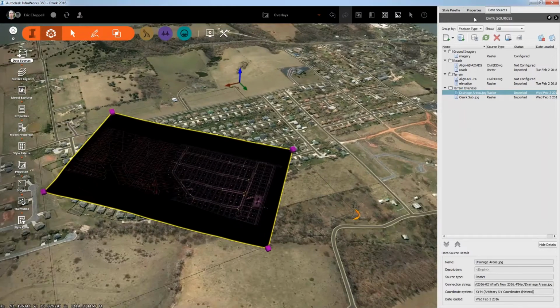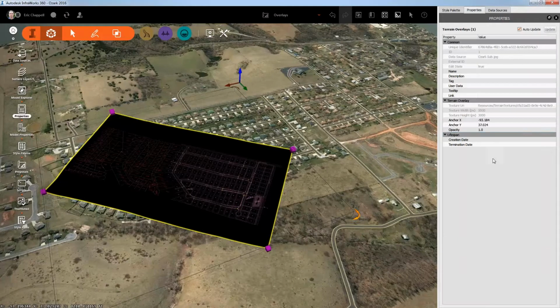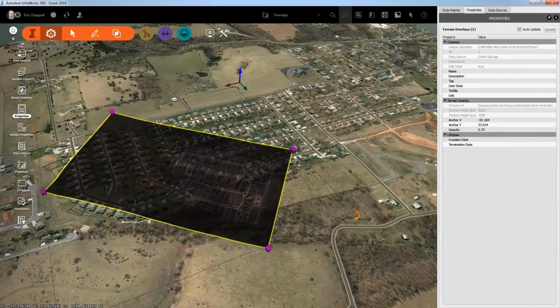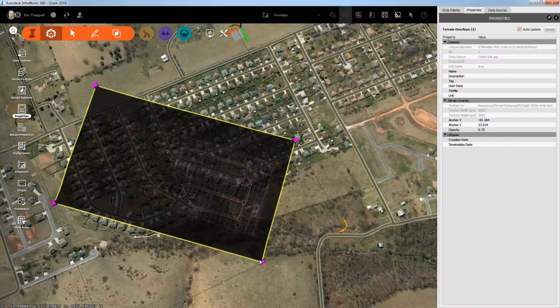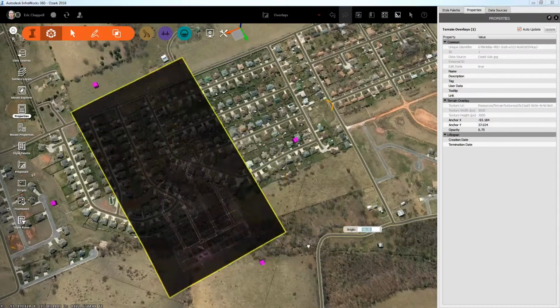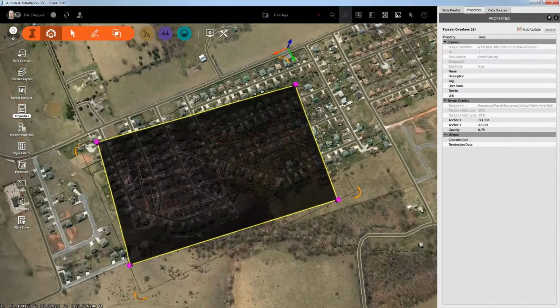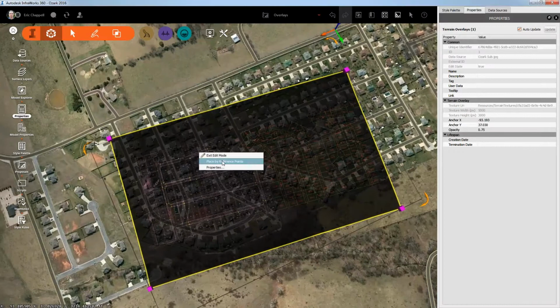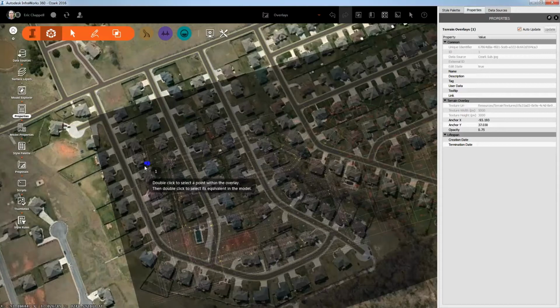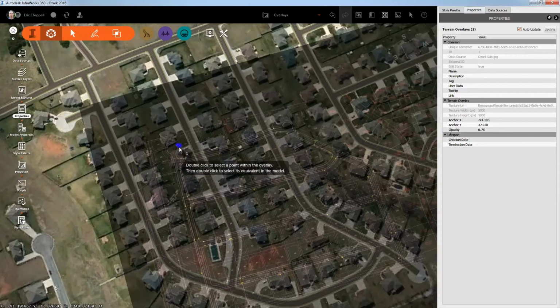Now typically what you're going to want to do is align this image with some features in your model to line things up, put things where they're supposed to go. So in that case you're probably going to want to turn on opacity. So I'll set this to 0.75. Let's say that's been pretty good to me. And then you can take this and kind of rough it into place. And then if you right click on the image, there's a place by reference points option. So you can click that, and it's a matter of matching up 3 points.